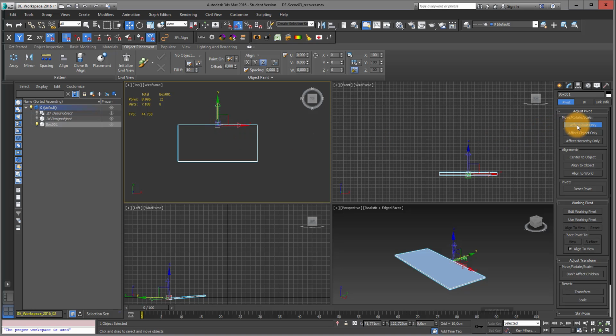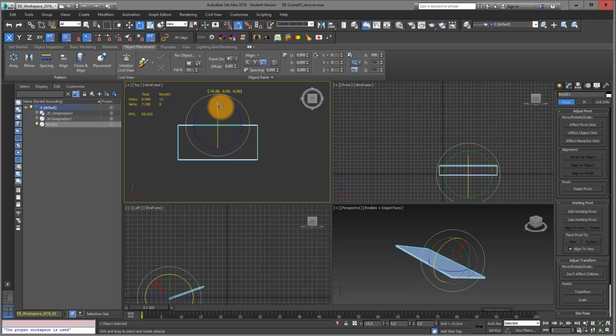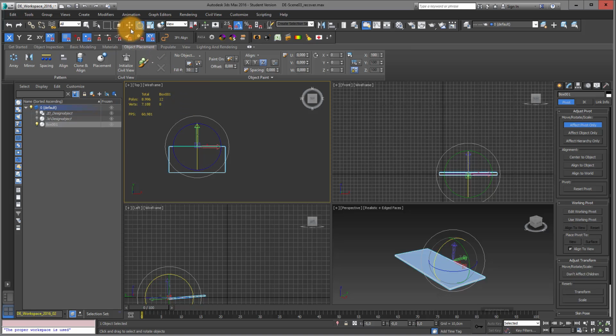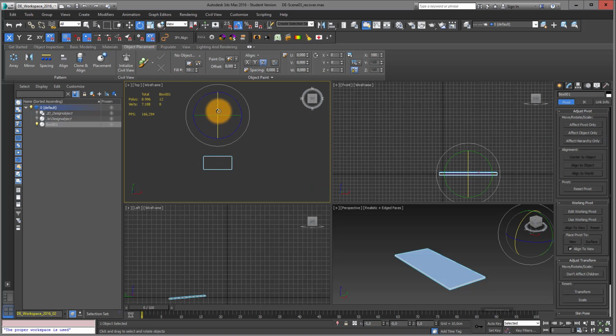And it's important that you switch off effect pivot point afterwards. Otherwise, you're constantly moving and turning only the pivot point. But if I switch it off and go into rotate, then you can see that you can rotate it the way you want to. And I can go again into pivot point, also move it completely somewhere else. You can also relate it to another object, by the way. And again, I switch off effect pivot point and I rotate it again.